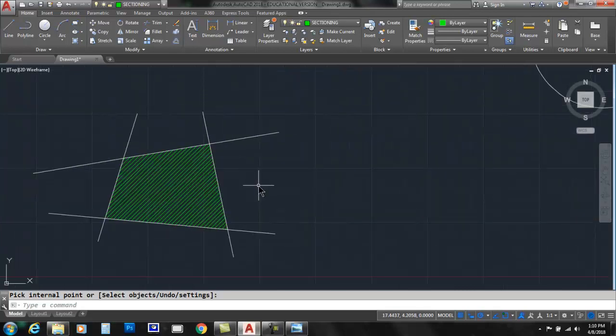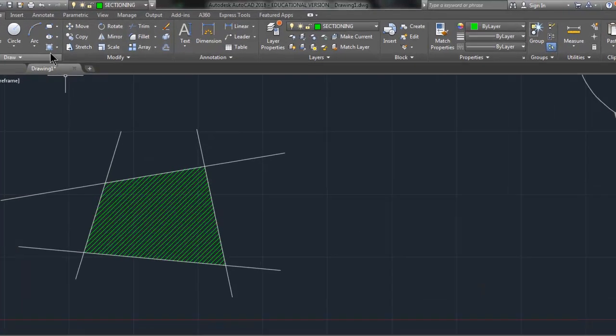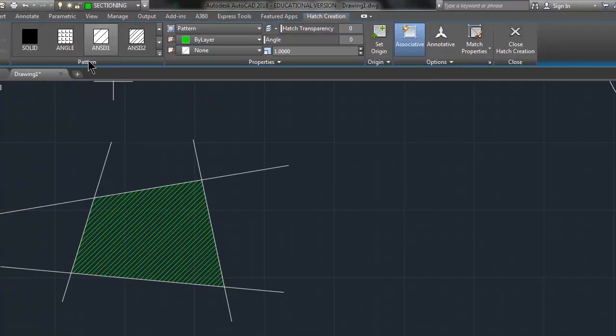Alright, so here we have lines. This is your classic sectioning symbol. This is really known as a generic hatch. It could be used for anything, but typically if you were creating a drawing of official purpose, meaning you were going to publish it for a patent, for a textbook, you would want to use a symbol that represents the material that has been cut. Alright, so if I go back and pick the hatch button again, this material is known as ANSI 31.